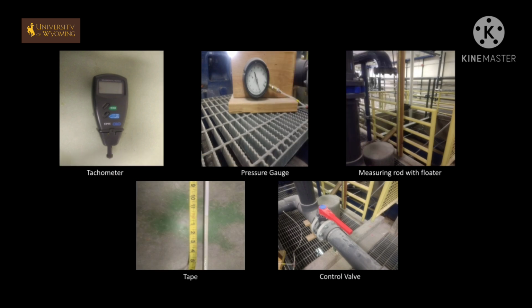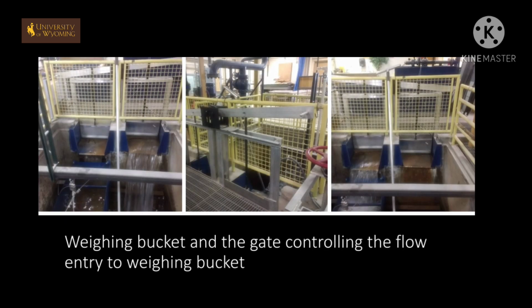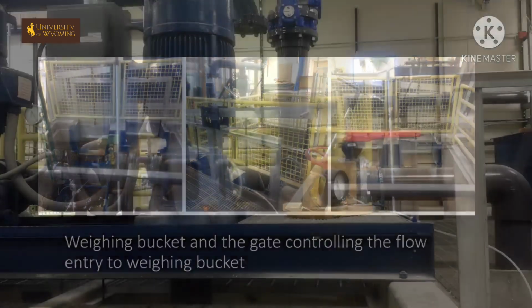Other instruments used in this experiment are the tachometer, which measures the rotation speed, the pressure gauge, which displays the pressure inside the pump, a measuring rod and the flow tape, which shows the depth of the water, and the control valve, which controls the discharge in the pump. To calculate the discharge rate, we'll use the weighing bucket, which you have used in our last experiments.